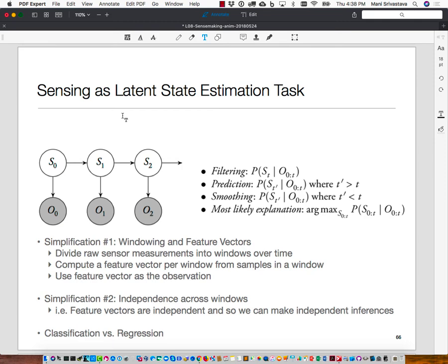Let's say even if we take a 1 second window, okay? If my accelerometer is being sampled at, let's say, a kilohertz, so I have 1,000 samples from the accelerometer, and I have, let's say, 3 inertial sensors, that's a total of 9,000 values, or kilobytes of that order of data, just from a second. So it's a fair bit of data if I were to be looking at that window. So features looking at only a small number of attributes can help there. What else do you think can benefit from doing features?